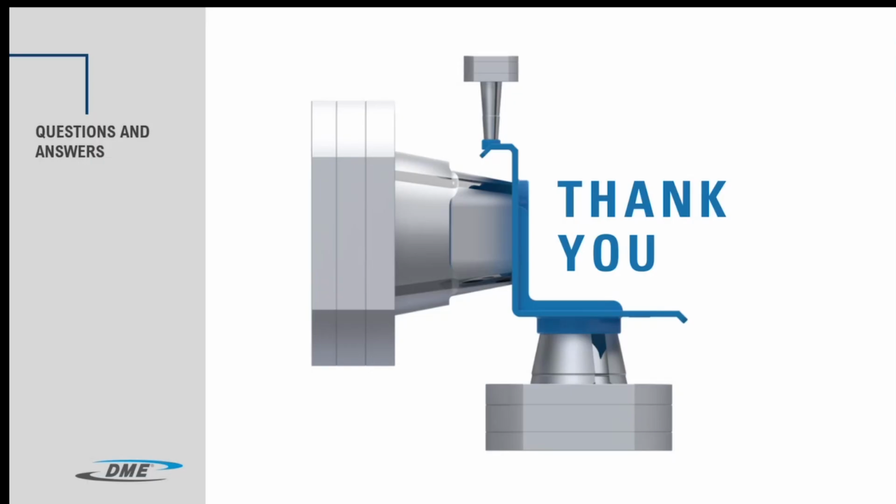Usually for soft material we can try with the normal material. Usually we are using 1.2344 as the material grade. So for unfilled material, we can use that. For filled material, like 30 to 50% GF filled material, we recommend going with the DLC coating. That will give a better output and reduce the wear. Okay.